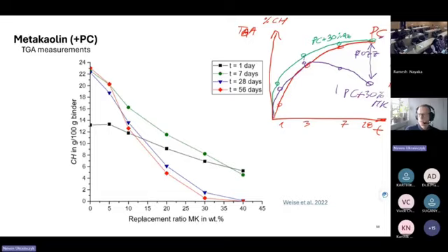You just need a reference. You are just wondering how much of that SCM reacts compared to the reference. And maybe even that reference already has some pozzolanic reaction, but you are calculating how much it reacts compared to the reference. Yes, I think it's possible. And the reference can already be something pozzolanic, or any type of limestone cement. Why not add fibers?